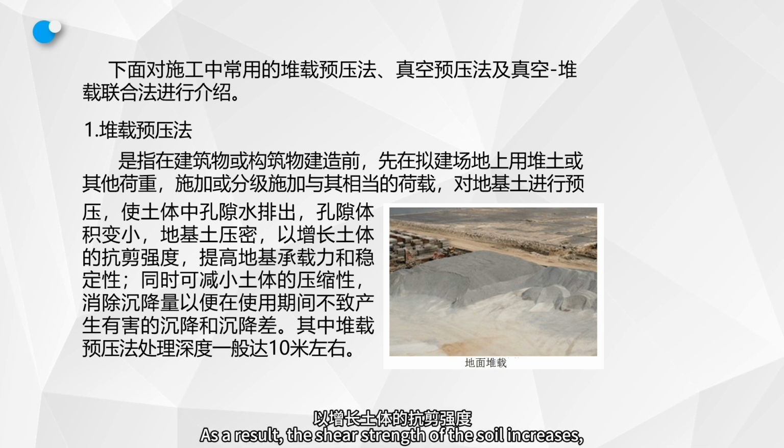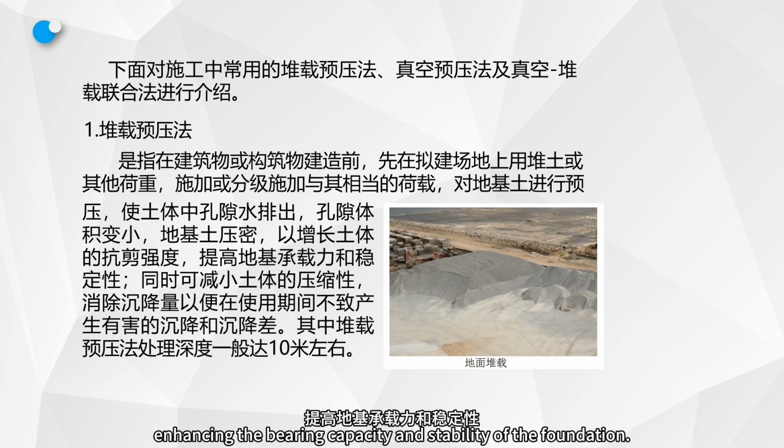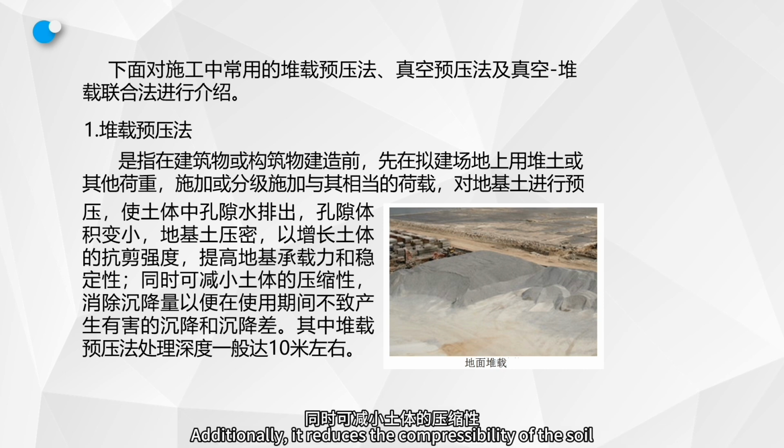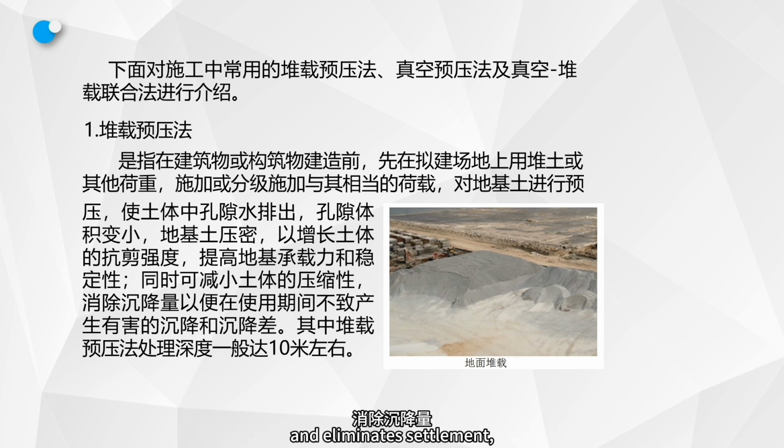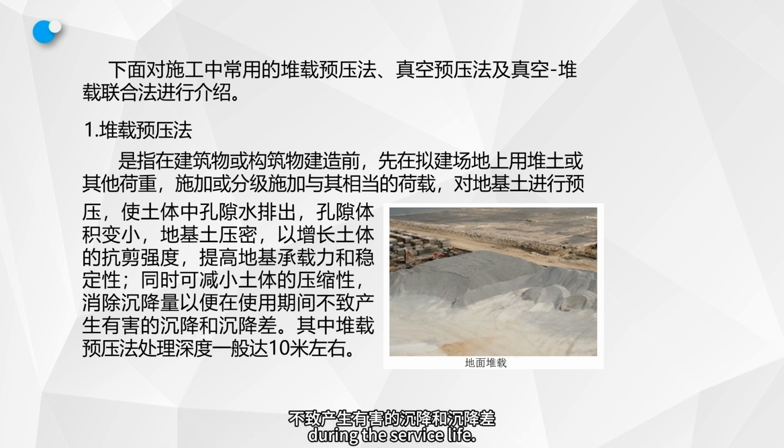As a result, the shear strength of the soil increases, enhancing the bearing capacity and stability of the foundation. Additionally, it reduces the compressibility of the soil and eliminates settlement, preventing detrimental settlement and differential settlement during the service life. The treatment depth achievable with the surcharge preloading method is generally around 10 meters.